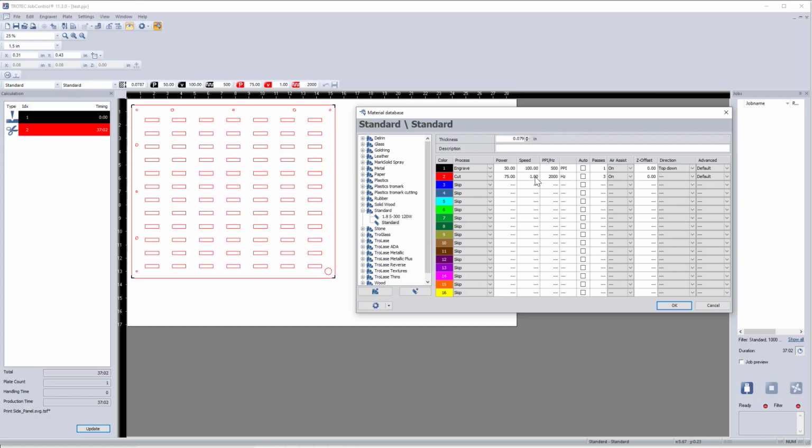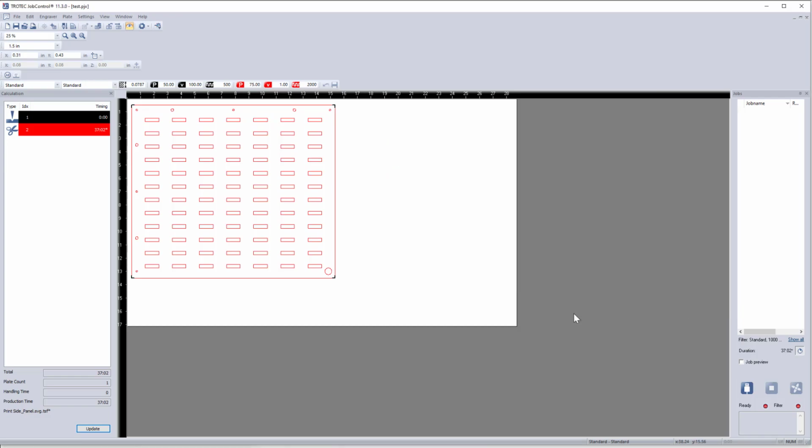In many cases, you'll be able to rely on the path parameters that we've identified for the material systems that we have, and use them for your actual prints. So you can update that, and I'll just put in an arbitrary number here. If I increase the speed, you should see that after I update, this will reduce the time required to make your components. The challenge is: what are the right parameters to use here? We do recommend that you use the recommended parameters that we have.